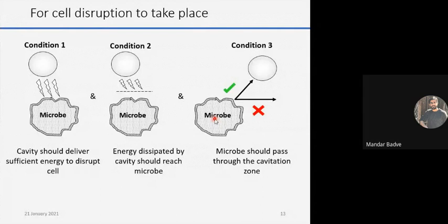These are conditions to enhance the effectiveness of your cavitation operation, based on your application. If you're talking about wastewater treatment, what we want is for the cavitation to generate sufficient energy to break a water molecule into the highly reactive hydroxyl radical. In that case, your first condition should be that the cavity delivers sufficient energy to form the hydroxyl radical.